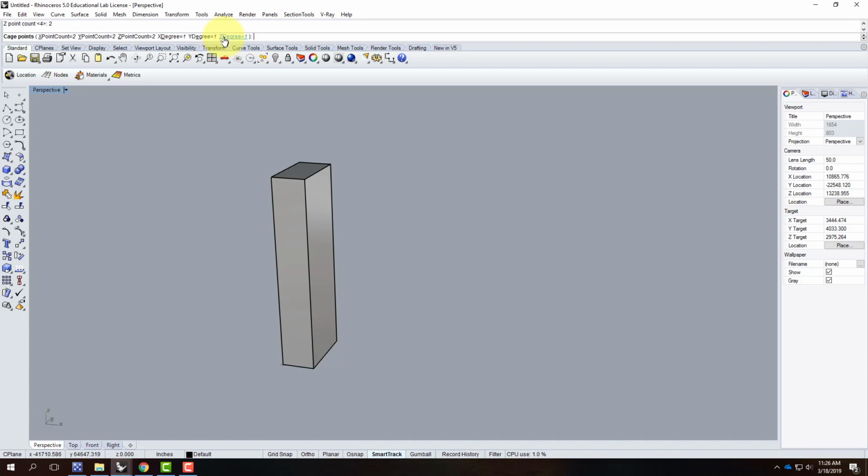So we'll go ahead and say OK, and I'll press enter. Region to edit global, one more enter, and there we go. And you say, wait a minute, nothing happened. Well, something did happen. I have little control points on all the corners of my bounding box. It looks like they're the corners of the object, but it's actually the corners of the bounding box that contains my objects.